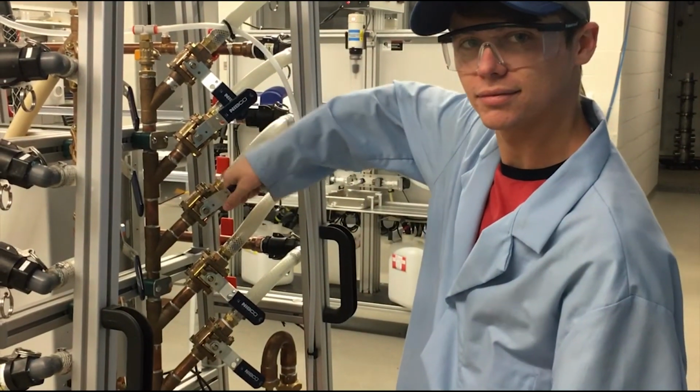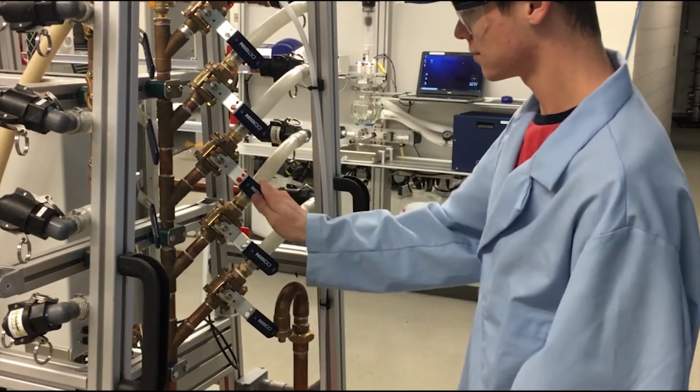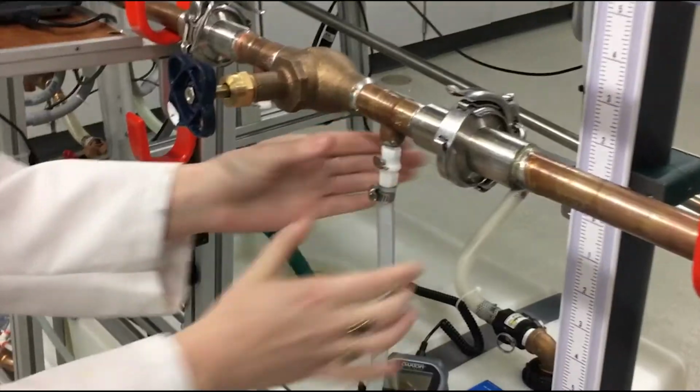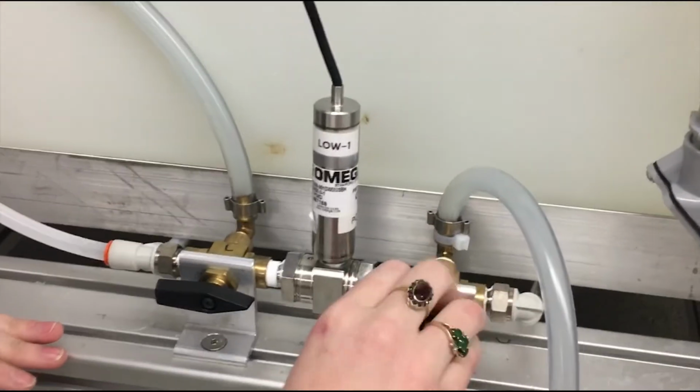Now it's time to start the pump. Turn the frequency up slowly until the water is being pumped at a high flow rate. This will help remove air bubbles trapped in the pipe. To further remove bubbles, reverse the pressure transducer lines or choke the valve at the end of the pipe.